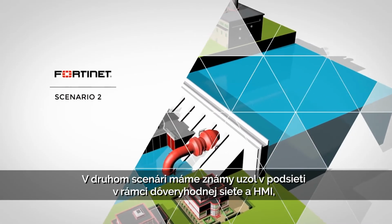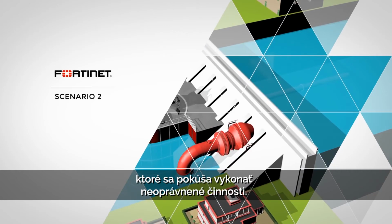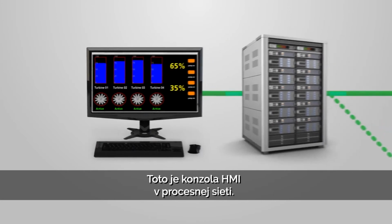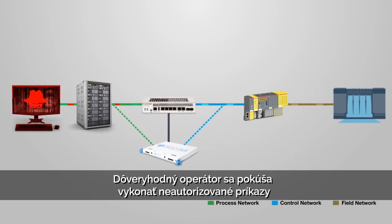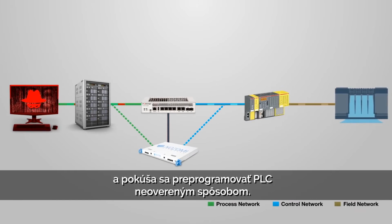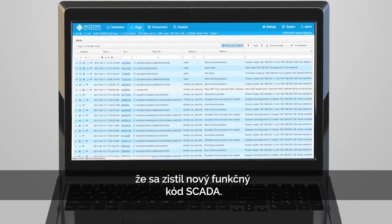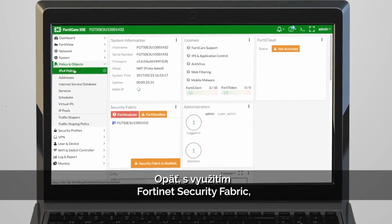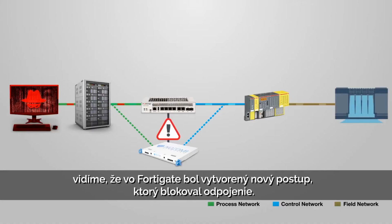In our second scenario, we have a known node within the Trusted Process Network subnet, the Human Machine Interface, or the HMI, that attempts to perform unauthorized actions. Here is the console of the HMI in the process network. A trusted operator attempts to execute unauthorized commands in an attempt to reprogram the PLC in an unverified manner. We can see that the SCADA Guardian has a new alert stating that a new SCADA function code is detected. Again, leveraging the Fortinet security fabric, we can see that a new policy has been generated in the Fortigate which has blocked this connection.